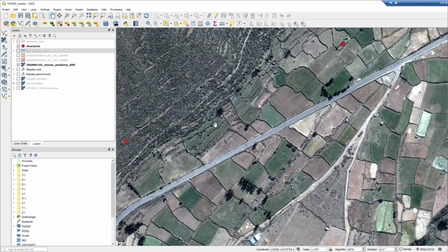Now this particular area is kind of degraded, so it's a good place to talk about abandoned versus unabandoned. It's actually more of a continuum. So these are unabandoned, in other words, they're in use, but they're kind of degraded. What happens is terrace faces can collapse over time. They need to be actively maintained because the water pressure builds up from the irrigation water that comes down. It can seep behind the terrace face, and the hydraulic pressure from behind can actually push out the terrace facing. That happens a lot, and other natural processes cause the terrace to slowly fall apart over time.